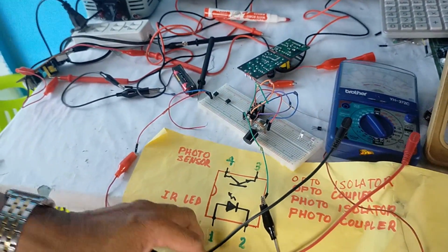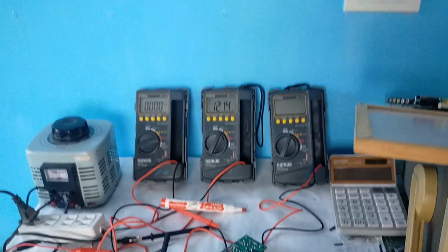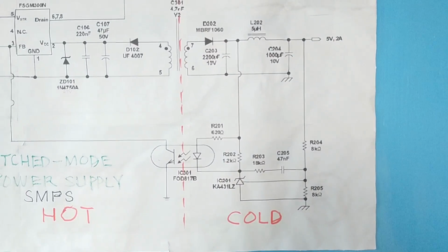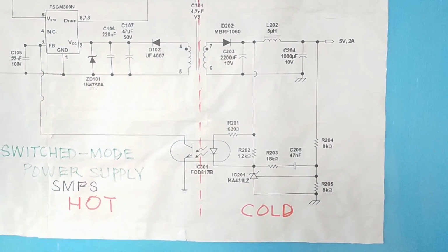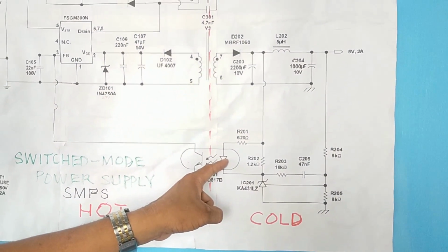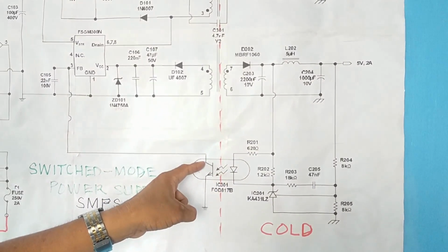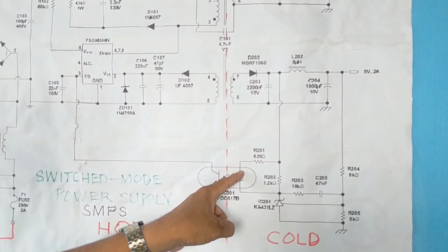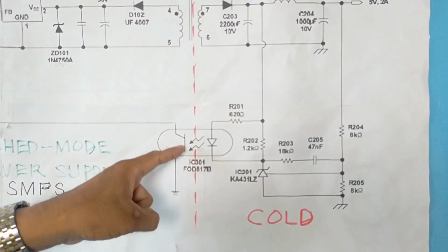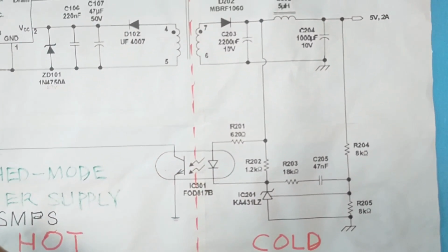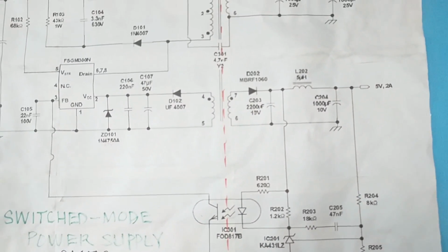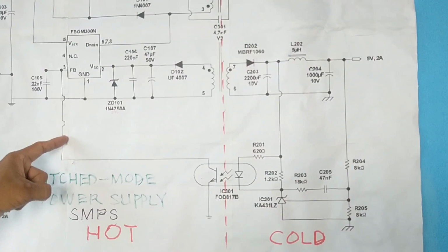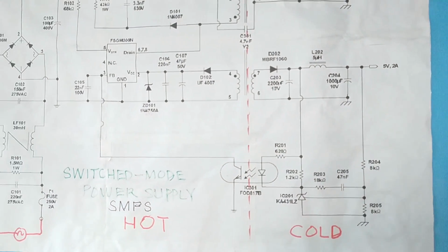That is to verify that the optocoupler, the phototransistor, and the light emitting diode here are not physically connected. So, the electrical signal is transferred to the other circuit by means of light. Once the LED emits light, the phototransistor, which is sensitive to light, that's why it is called photo, which is light, will be activated. It goes like that, class.